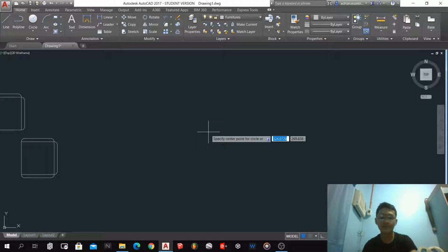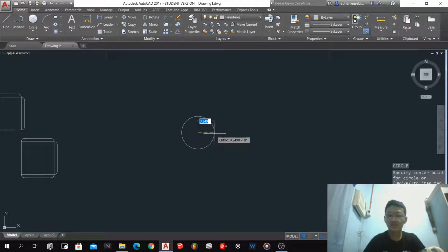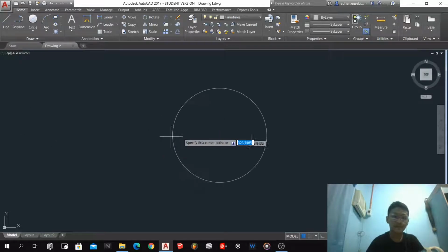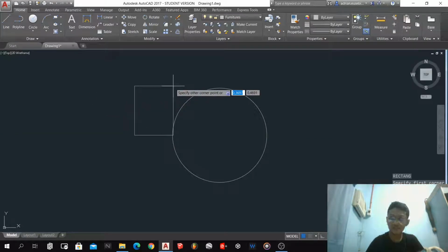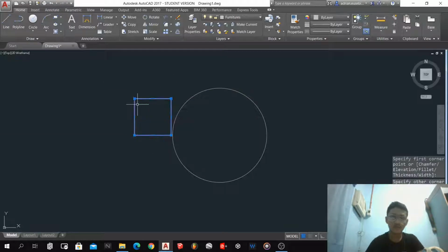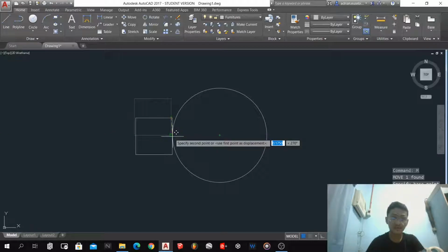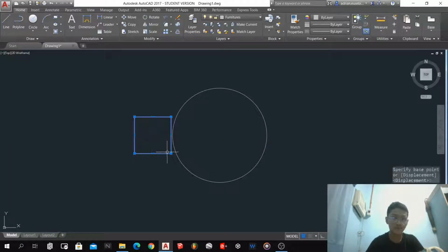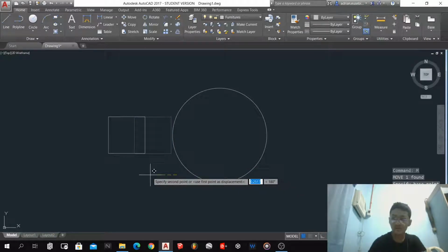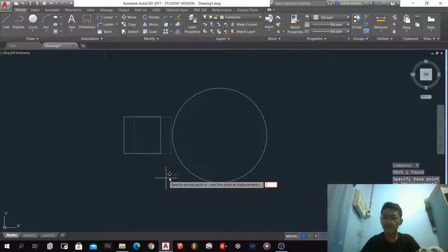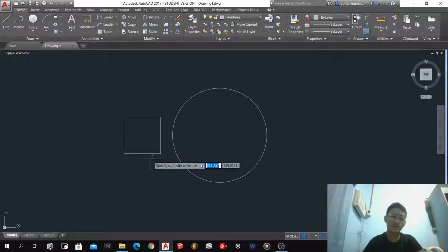So how to make that? So we have circle and type the radius, which is 0.45. Then after that, make a rectangle with 0.35 by 0.35. I think we're going to center this. Another move here by 0.1, 0.1, 0.1. After that, explode and offset this